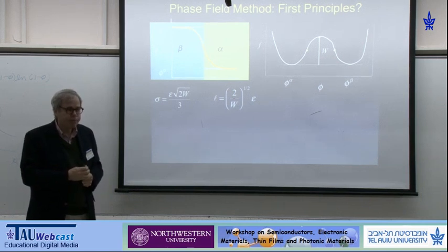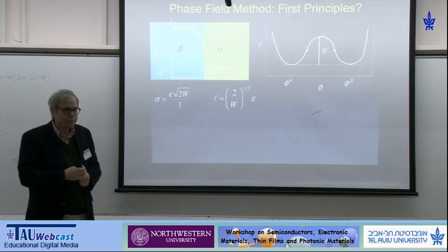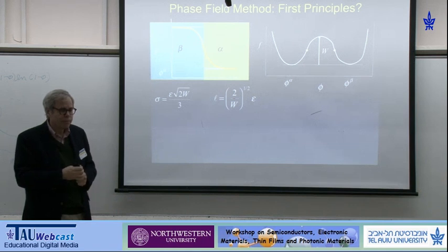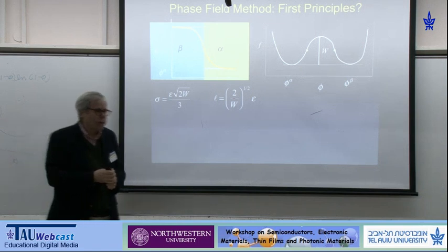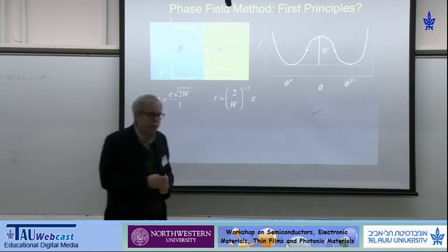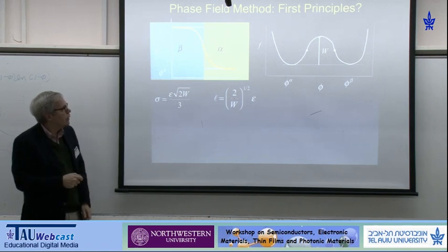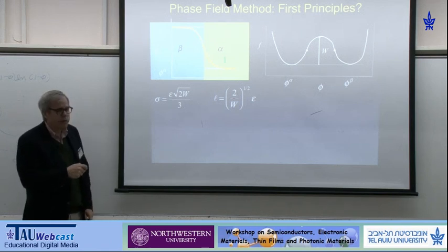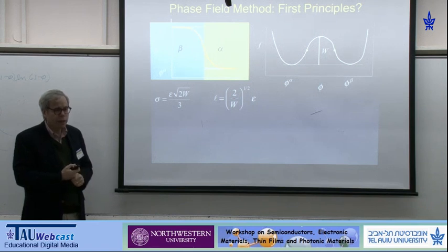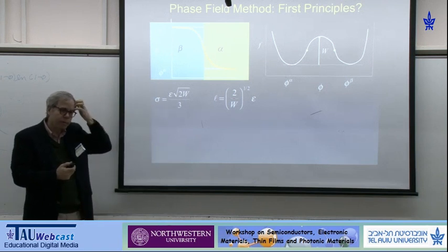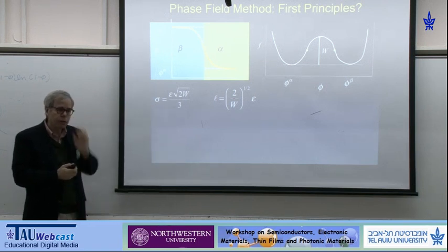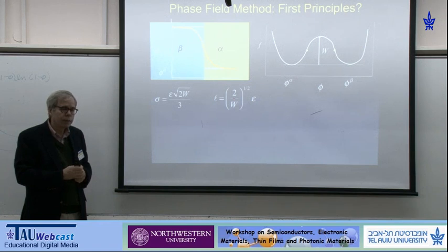Could you see with the phase field modeling this problem of the interfacial width associated with the precipitates continuously decreasing as the precipitates get bigger? That's an experimental fact. Yes, you can do that. The key in that case is to put together a model that accurately reflects the interface width in a real system, and you can do that if you choose the parameters the right way. It's certainly possible. Yeah, absolutely.